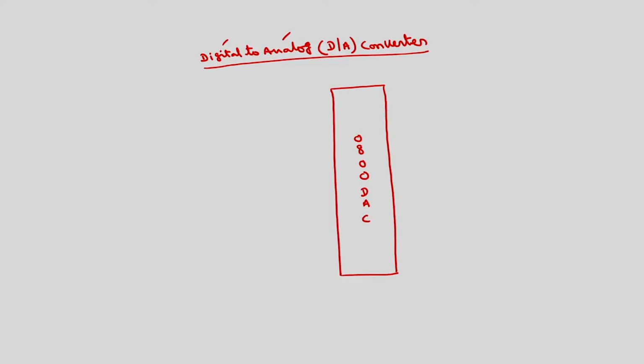So, the 16 pins of this D to A converter are, so we will be having 8 bit, this is 8 bit DAC, so 8 bit digital input, D7 to D0. The output will be current rather than the voltage. This is current I out, here I out will be there. This I out is proportional to the digital value. This has to be converted into voltage by using an external current to voltage converter, which can be implemented by using an operational amplifier. This is V out.